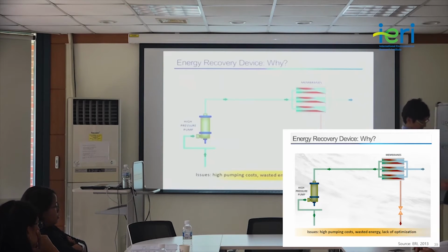It means that more than 50% of the energy is not used during this reverse osmosis process, and this energy is wasted. Without recovering this energy, we cannot improve the energy efficiency. So the role of the energy recovery device is to recover this energy and deliver it to the feed side of the membrane module